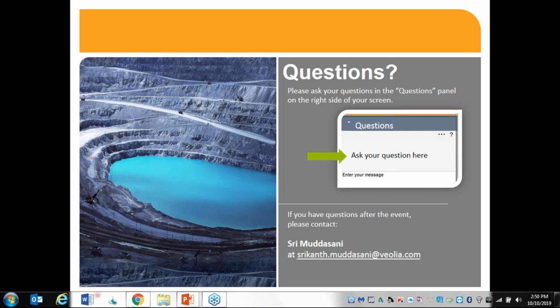What happens is if you send it back, the sulfates will never break down. But if your tailing pond is acidic in nature, then that starts to break down the ettringite molecule, and then the sulfates are released. So I would say send it to landfill, until your tailing pond does not have low pH. Okay.